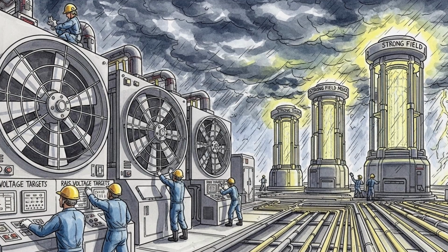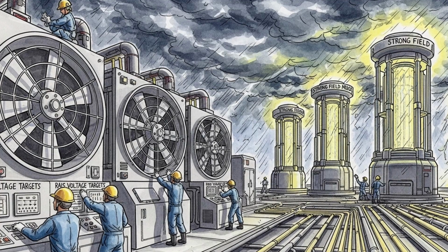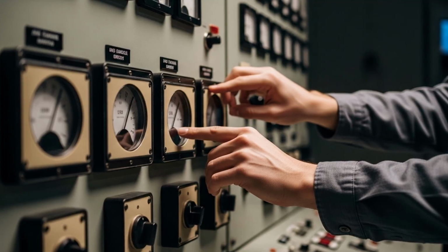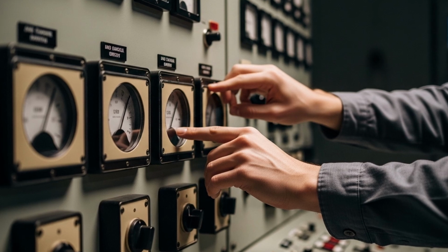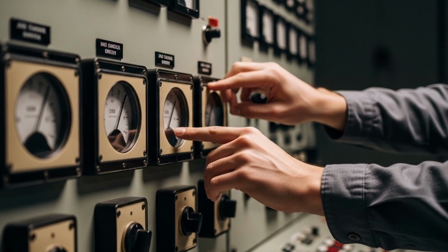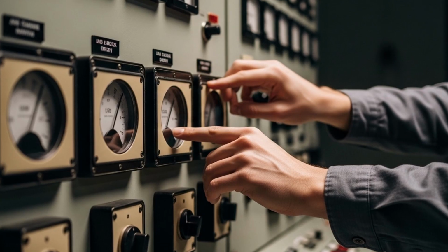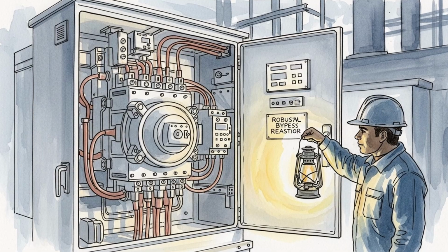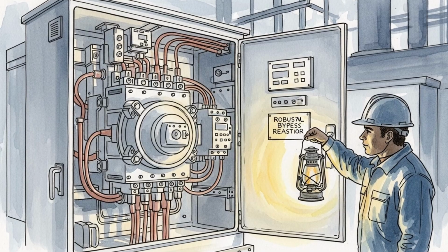Power transformers are vulnerable because geomagnetically induced currents add a direct current bias to their windings. This bias can push the magnetic core towards saturation during parts of the AC cycle. Partial saturation increases reactive power demand, heats windings and structural parts, and distorts waveforms. Protection devices designed to trip for faults can misinterpret the distorted signals or operate with delay. If many transformers in a region enter stress states together, system-level voltage support can collapse and trigger widespread trips.